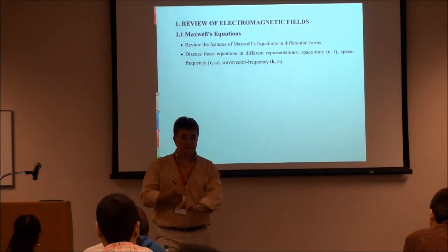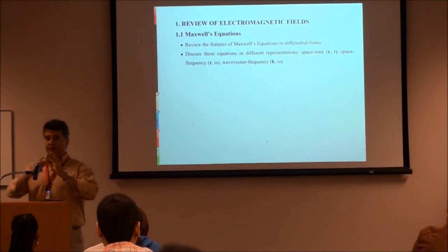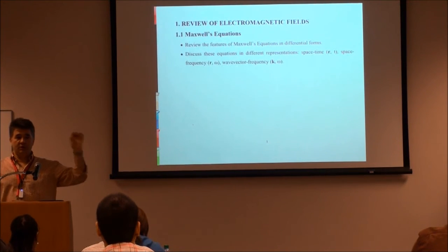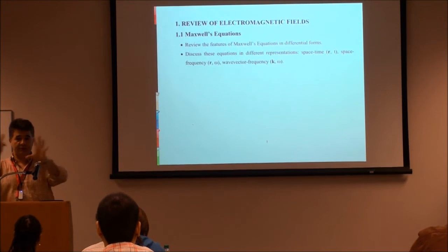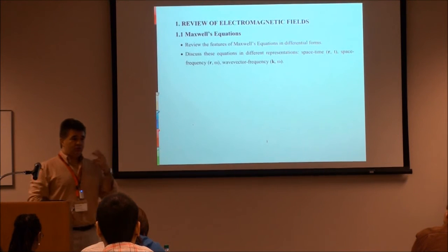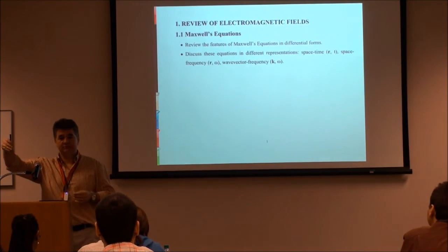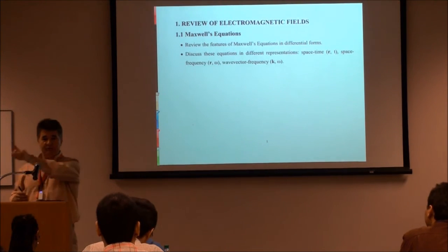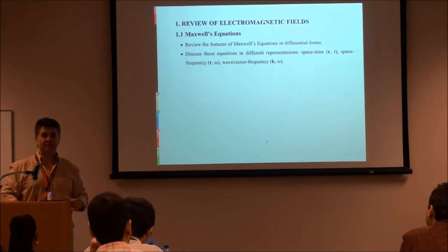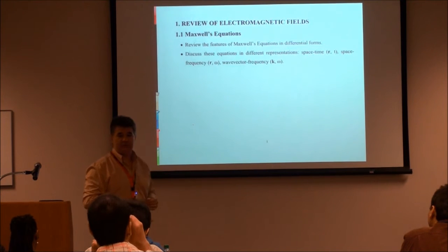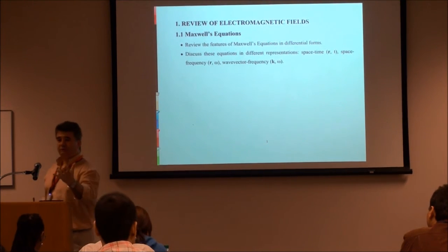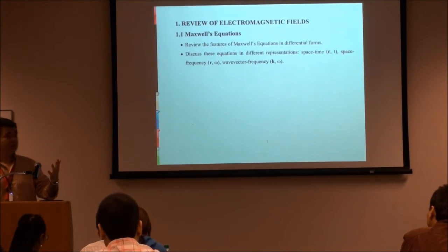So what did we learn? Linear systems allow me to break an input into small pieces, solve each piece, add the results. Two ways of doing this. One, I break my input into a succession of delta functions. I can solve for each delta function, add up the results. That's what is called the Green's method. The result comes out to be a convolution between the input and the impulse response.